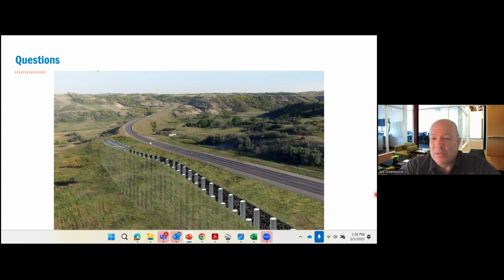I will say here we were limited by the right-of-way constraints. I would have loved to have an inclinometer down at the toe just to confirm that we had the right shear zone and the right dip for that layer. So we had to kind of rely on the geologic mapping in that area. But we did a back analysis, and when you do a back analysis and start from a factor of safety of 1.00, that kind of covers some sins.